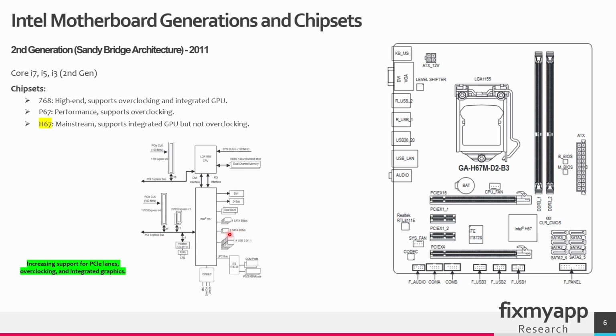So in total we have 6 SATA connectors, and those 6 connectors you can find on the mainboard. This chipset also supports dual BIOS. If you look at the mainboard, there is a master BIOS and a backup BIOS. When the CPU supports integrated GPU, then the signal will be sent to the chipset, and from here it will